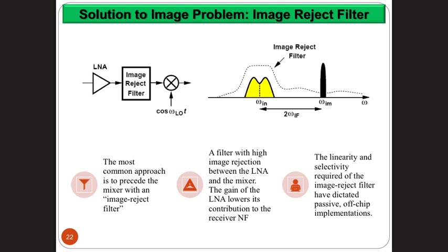And if that's for the band selection, and if we do that, we might end up with too much restrictions on rejecting our image. So we typically don't. We use another filter separate from this for the band selection, and then we put the image rejection filter. Then our signal is brought into the IF stage where we do the channel selection filter, and then our signal is brought down to its baseband.